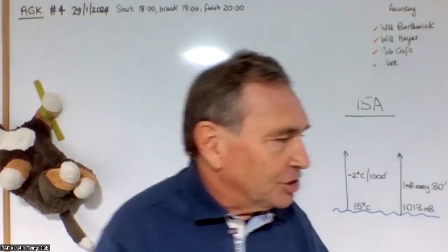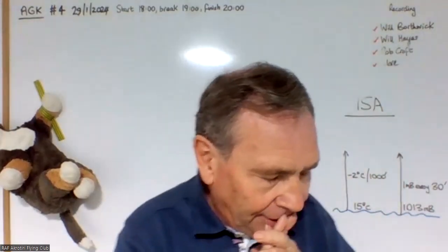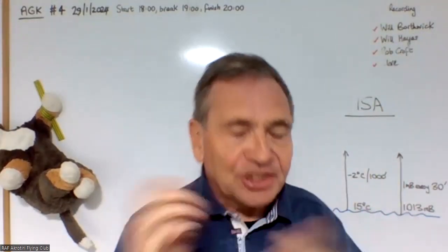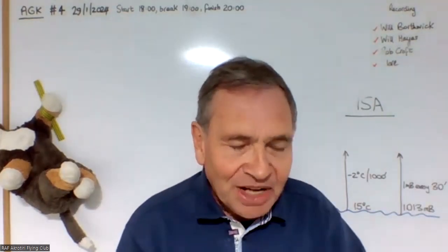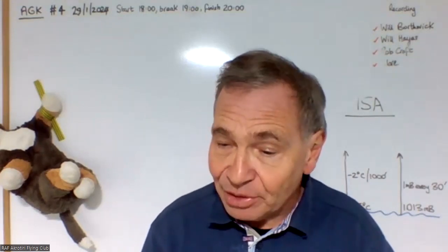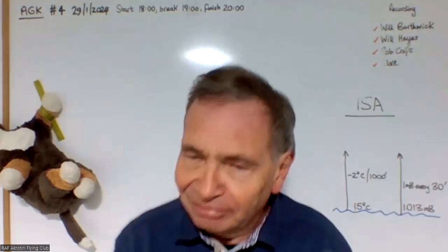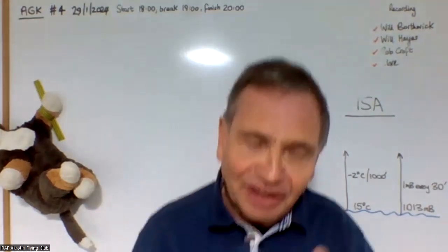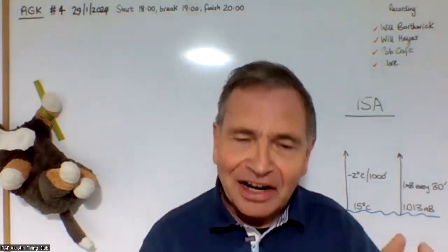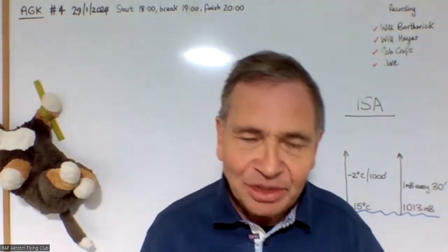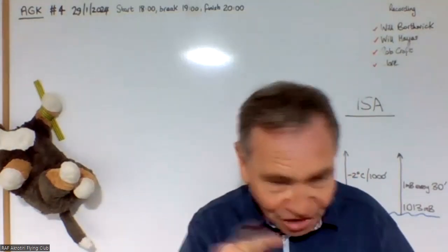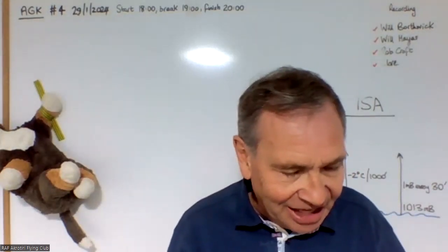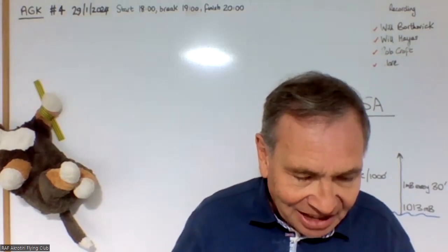An interesting thing to realize is that on the back of the instrument that's air driven, it just basically has an air in and an air out. And the instrument doesn't actually know if it's having air sucked out of it or air pushed into it. All it's interested in is that there's a 2 pounds per square inch differential between the in and the out.